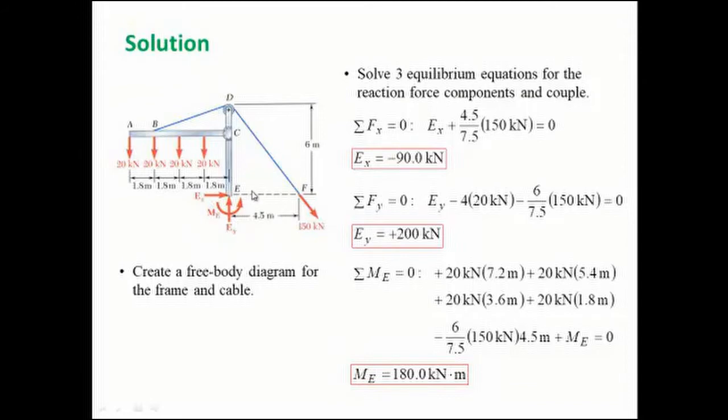This problem can also be solved in a different manner. As you know, the definition of free body diagram, we have to isolate all the bodies, and then we have to solve. Now if I am isolating this pulley, it's a frictionless pulley, it is treated as hinges, so there will be 2 reactions, and this tension will be acting here, this tension will be acting there. Both tension forces are equal, 150 Newton, but the inclination is different.